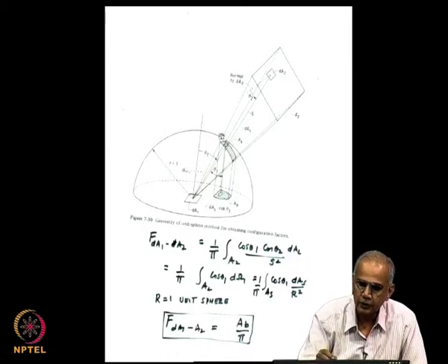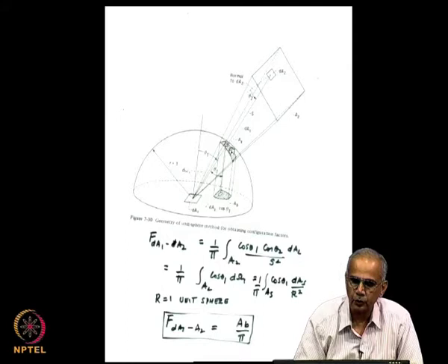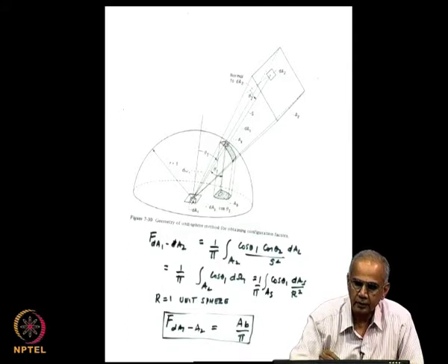Now, when you come on the sphere, the big advantage is that the line joining the center of this hemisphere to the object here, dAS, is normal to that line. So, theta 2 here is 90 degrees, so that will go away.